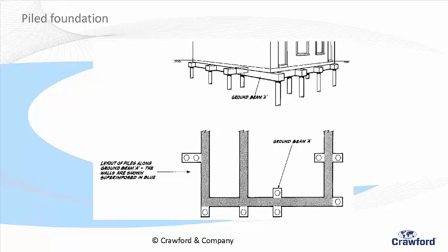So we are now going deeper. We're saying this tree and its influences are about 4, 5, 6, 7 metres, or there are other problems, peat for instance. We need to pile, we need to go deep. Piles will go down to 20